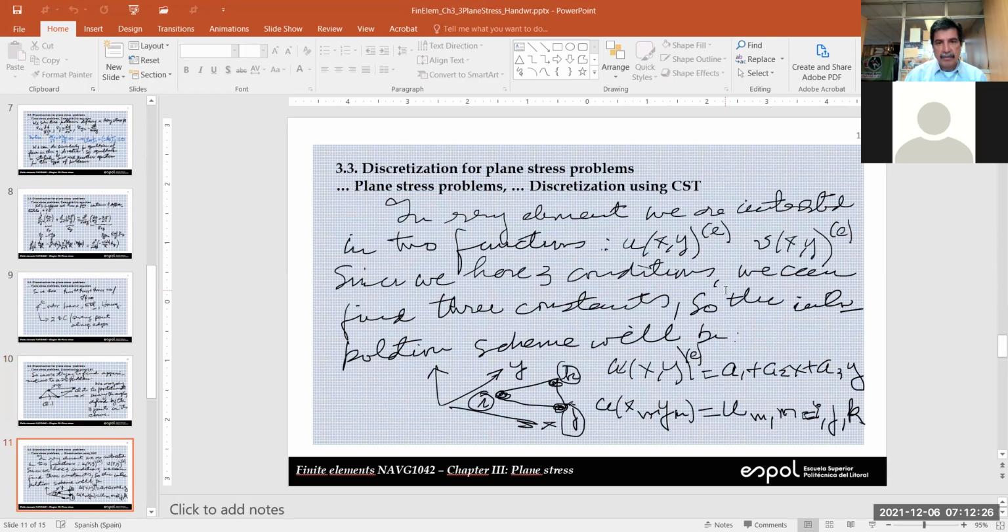Okay, so we said that we're going to use triangular elements in order to partition our domain. Our domain now has 2 dimensions. It's a little bit more complex than what we had before. In this case, we use the simplest element, which is a triangular element defined with nodal values at the corners, 3 corners, of course. So we could use a polynomial which includes 3 terms. So we decided to use this linear polynomial, but in 2 dimensions, x and y.